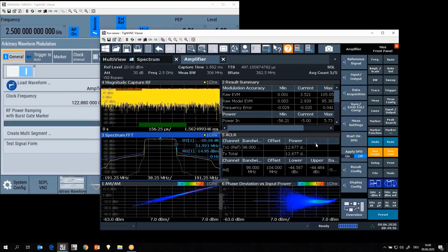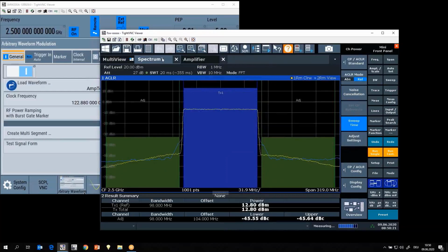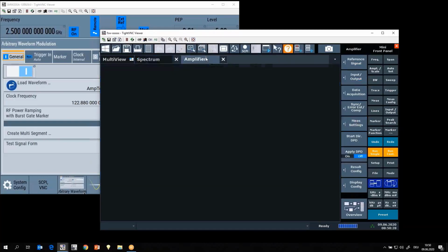And at this point, I want to get back to what I said in the very beginning, that the numbers we have in here are not calculated on the trace being plotted in the spectrum FFT plot. There is a very easy reason for that, because typically, if you do comparisons on ACLR, the reference is the spectrum analyzer, and the spectrum analyzer doesn't have IQ averaging.